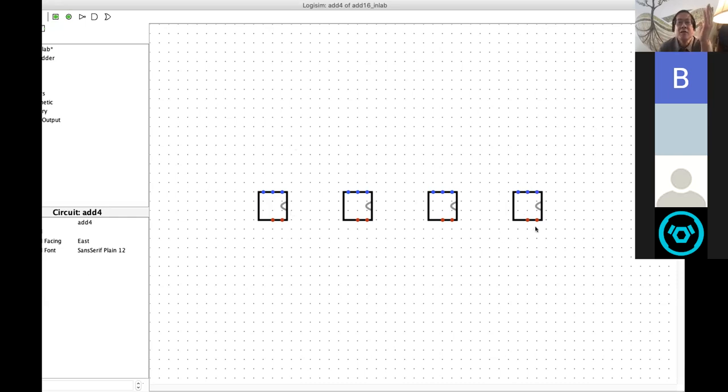Okay, so now what I want to do is connect. You see, if you mouse over, you know that's the C out part. You want to connect the C out to the C, and that's the C in. Now, note that the 3 inputs are symmetrical. If you remember that from when we designed the adder, it doesn't matter which of the 3 inputs you label C in or A or B, right?